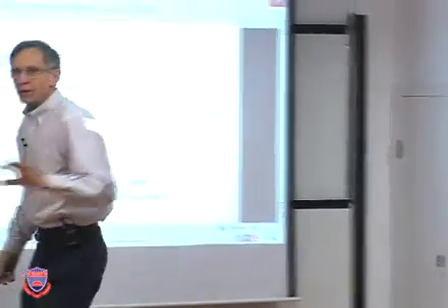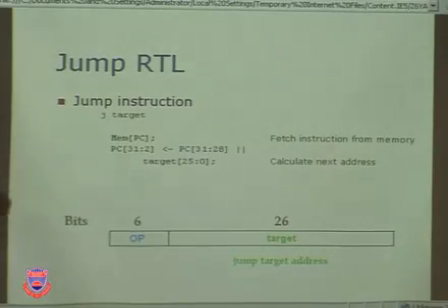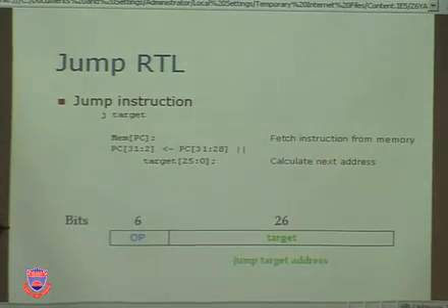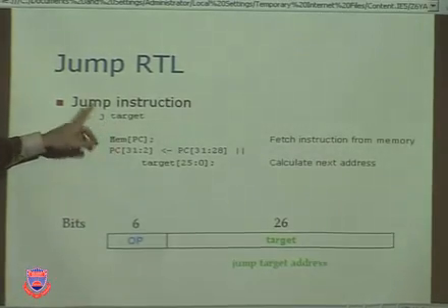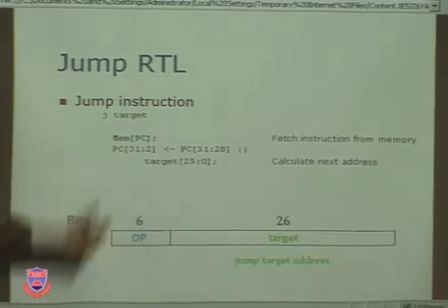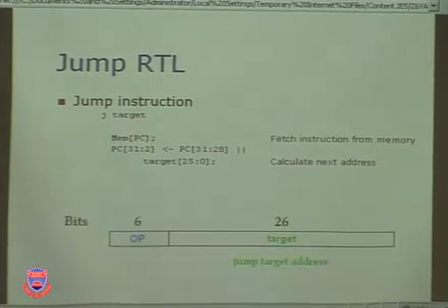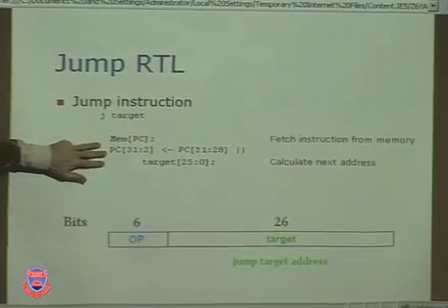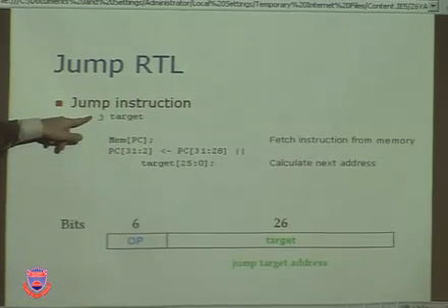Okay, let's go on. So our 9th instruction that we're going to build into our data path is the jump instruction. It's got a very simple syntax. Remember J and the target address. We're using pseudo-direct addressing. So here's the register transfer statements that come from this instruction.